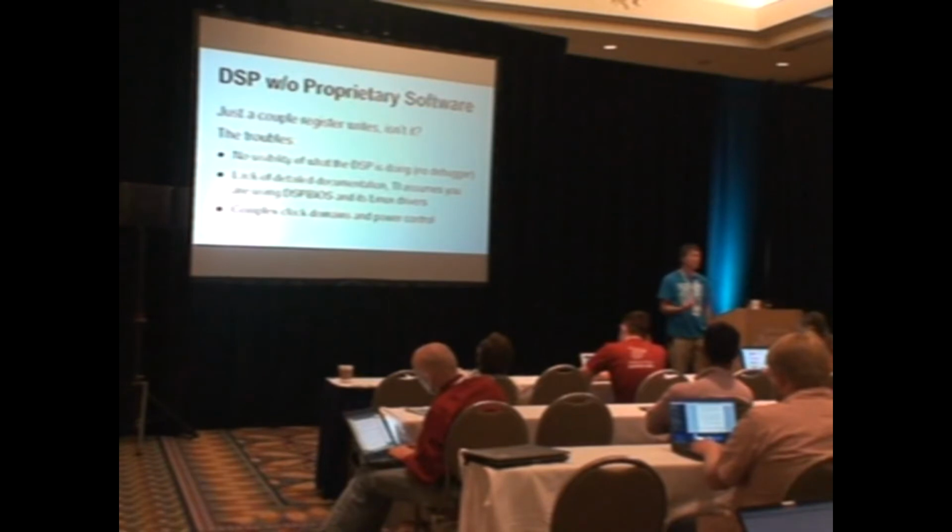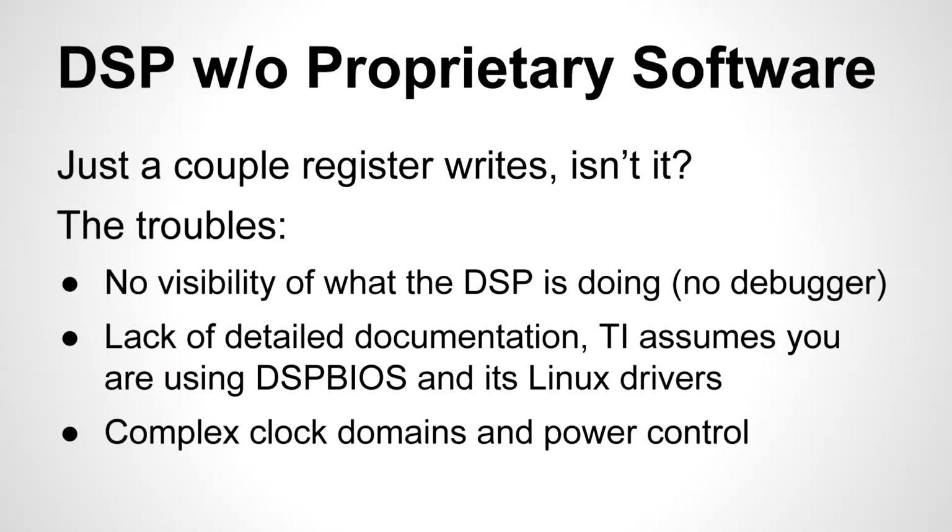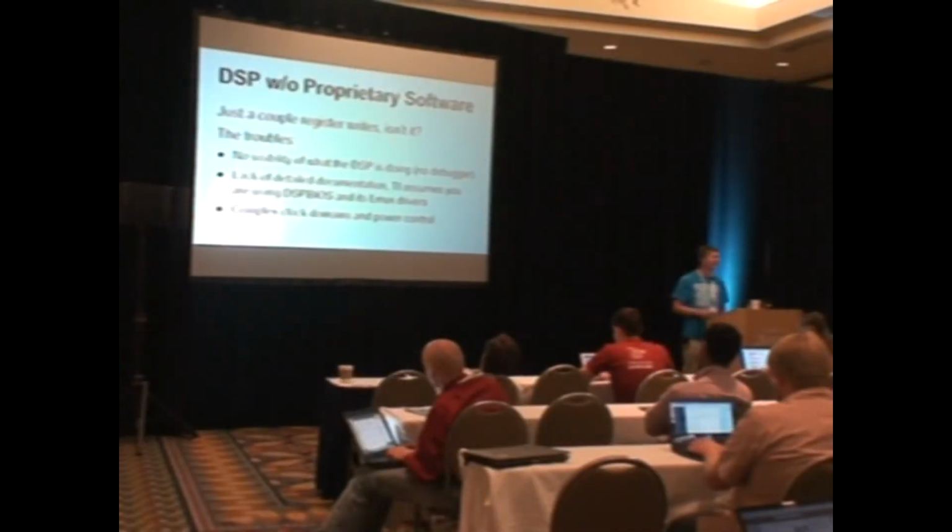One of the things he's been trying to do is avoid the use of proprietary software at a very extreme level. So he's basically doing bare metal on the DSPs. And apparently doing bare metal on the DSPs is painful, because TI has assumed that you're using DSP BIOS, so the documentation at that level apparently is painful. And you kind of have to worry about clock domains and power control and things. I have to say DSP BIOS is BSD license. Yes, yes. He basically did make a note that if this was asked, it is BSD licensed. He was confused earlier.